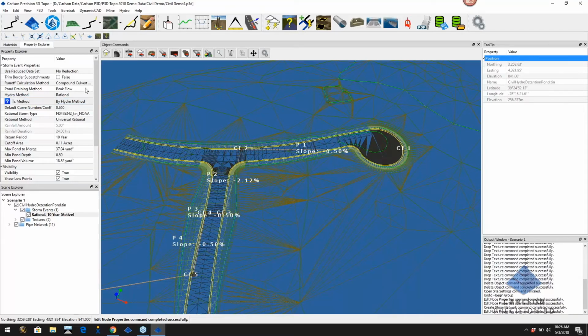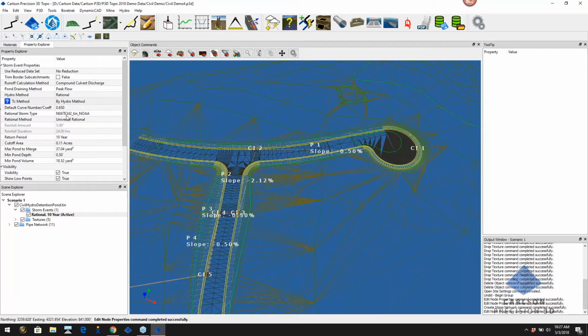We've also got, you can slide this over so I can show you, here's my storm event. So basically, no matter where you're at, if you are tied to your state plane coordinate system, you can come right here, click this button. We'll go out and ping the NOAA Atlas 14 maps for you and download those numbers automatically. Now some jurisdictions have their own, and you've got to go in there and set those up.